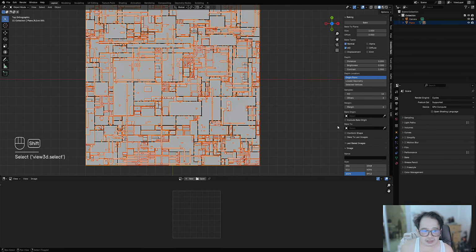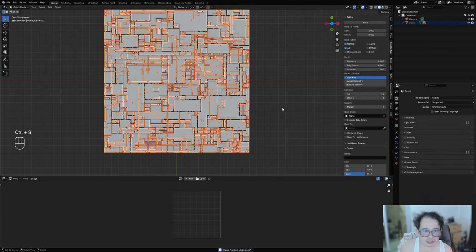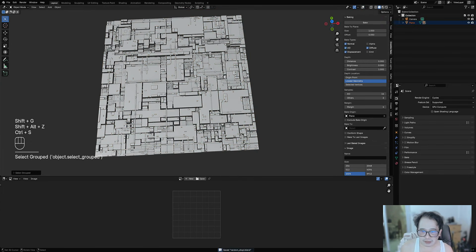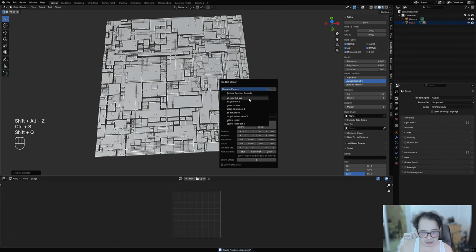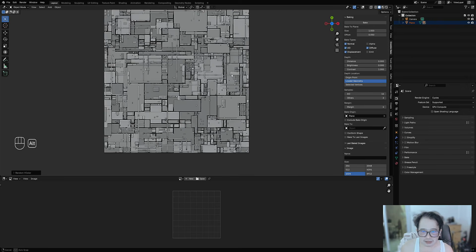So for these objects here, I'm going to use the plane from the selection as my bake origin and set the depth location to the lowest geometry. Normal, AO, displacement, and we're just going to bake this tree here, or probably we're also going to bake the diffuse. But first, I'm going to assign a vertex color to this, set it to island. There we go.